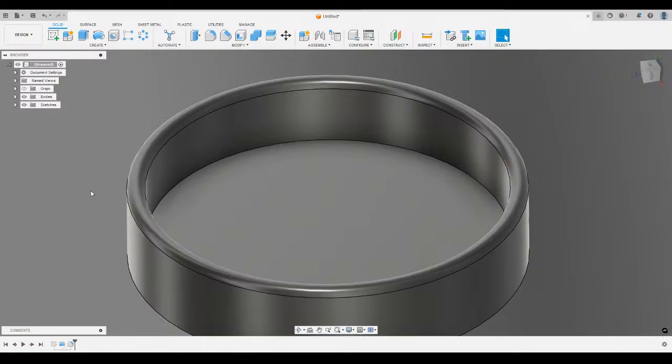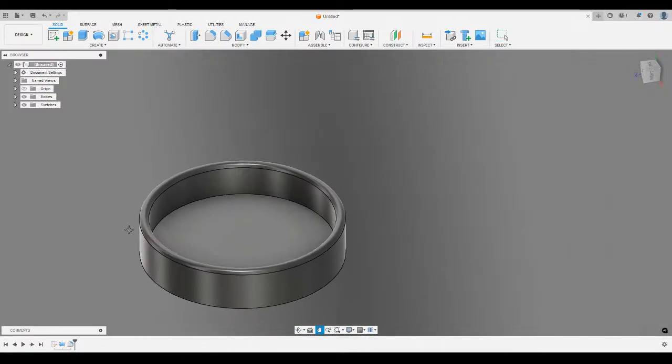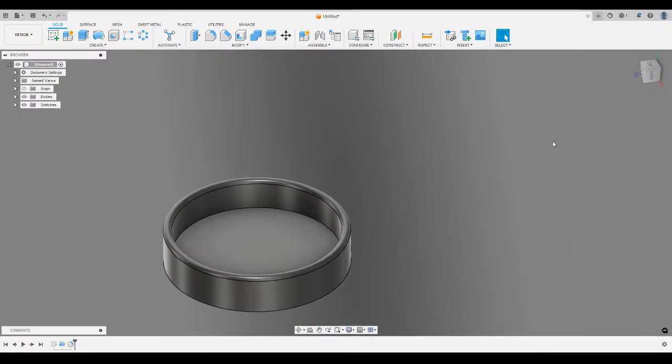Then also in 3D printing specifically, and in designing for 3D printing, because of how 3D printers work, it is also best to always round over your edges. Because in an FDM plastic extrusion 3D printer, when the print head is moving around, let's say you make a square, when it goes to print one wall, it's moving in a straight line one way.